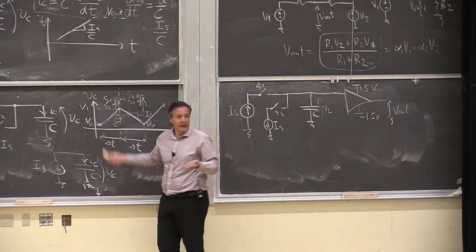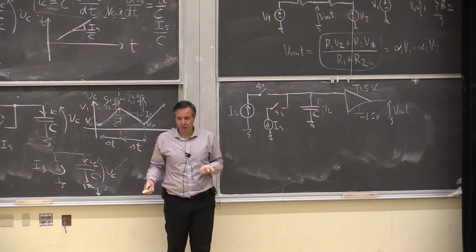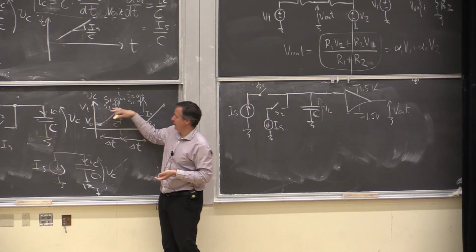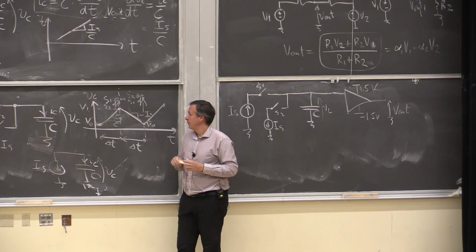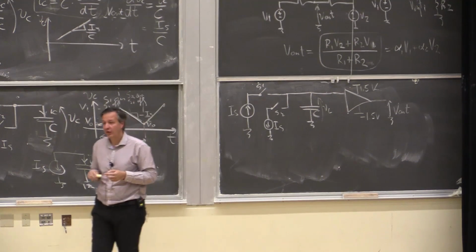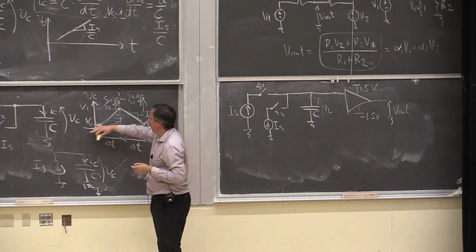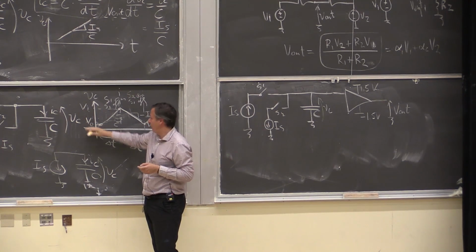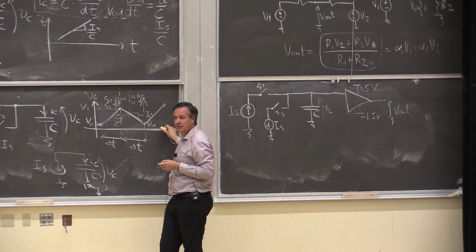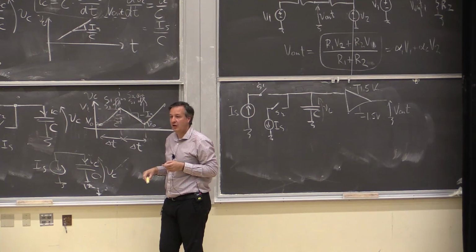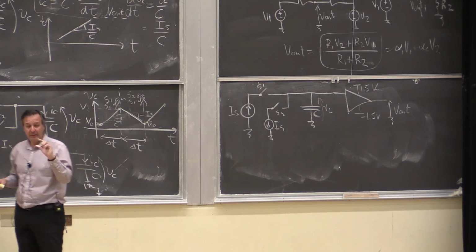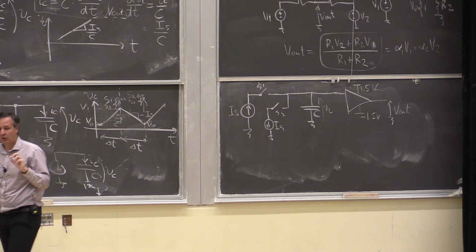So now what else do we need on that comparator to be able to generate the pulse train? Yeah, so where would we put that reference voltage? We put it at 0. So this is like V1 and V0. I don't know what these two values necessarily are. So if I put it at 0, I'm never going to cross. Remember, that's the output. The output will be toggling depending on V plus minus V minus.